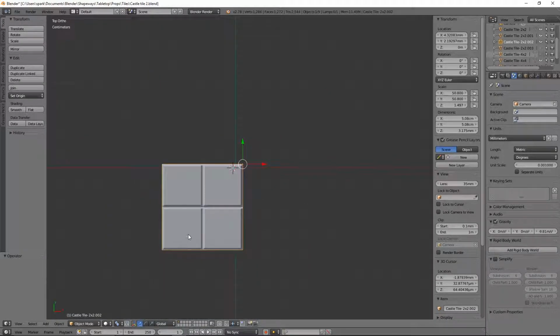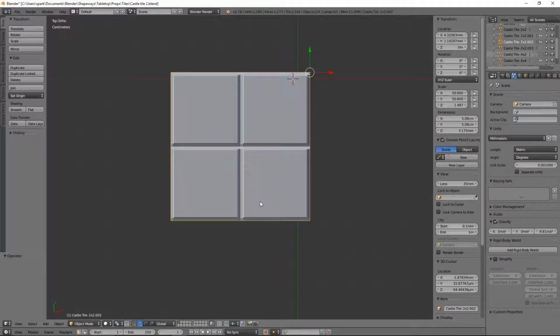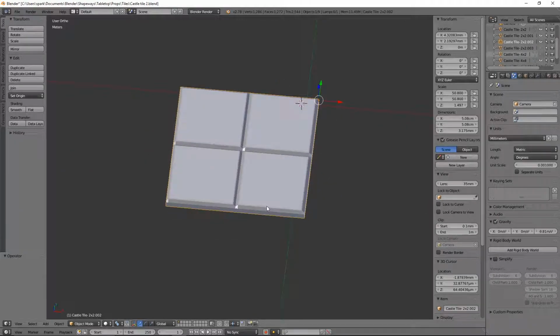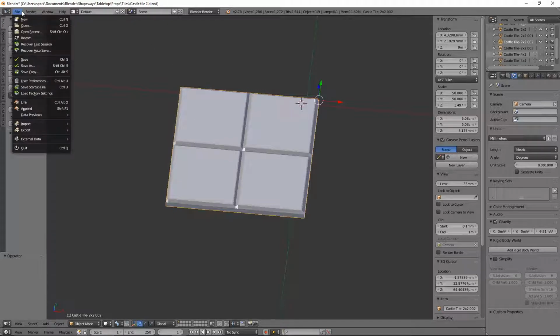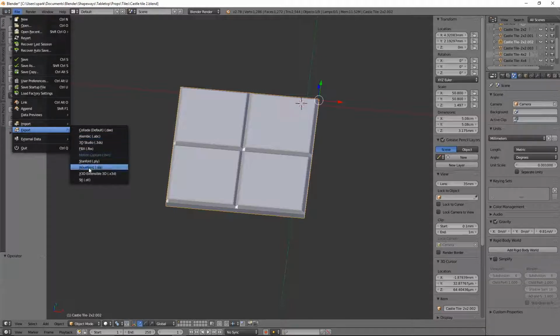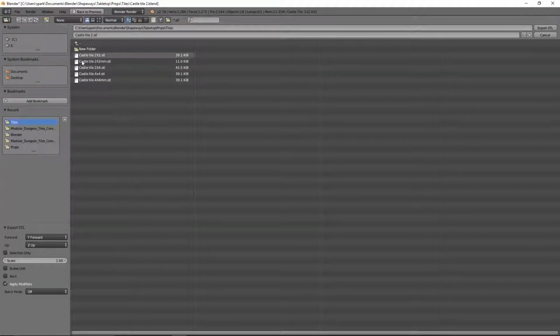Now you'll notice it gets a lot bigger. That's fine. That's what we want. Blender just shows millimeters in here much bigger. It'll still be 2 inches by 2 inches. So what you'll want to do, File, Export, STL, just like normal. I'll typically change it to a different file name since I still like to have my inches for Shapeways and other things like that. So for this one, I'll just add a mm so I know it's in millimeters.